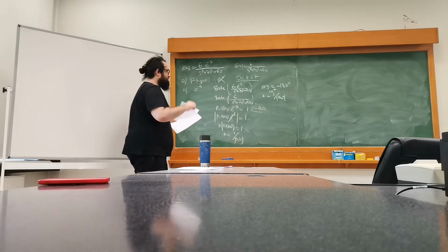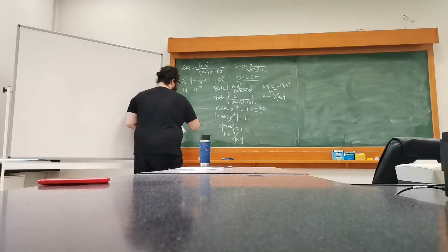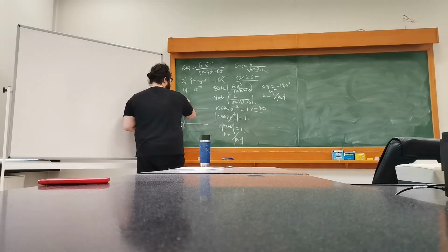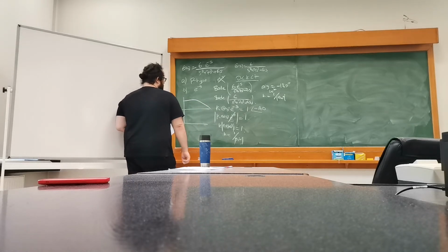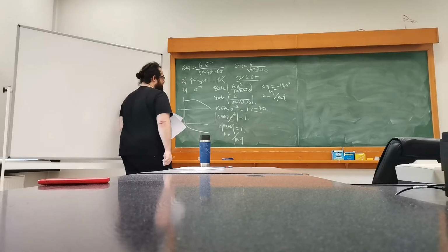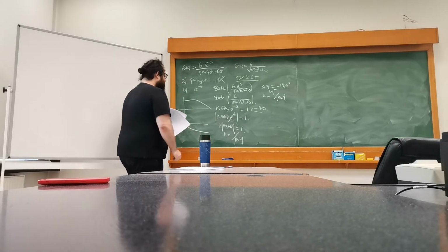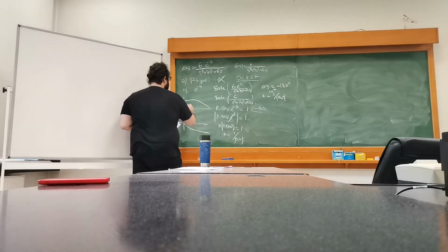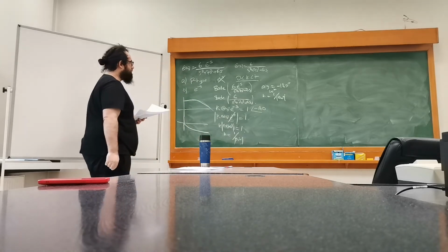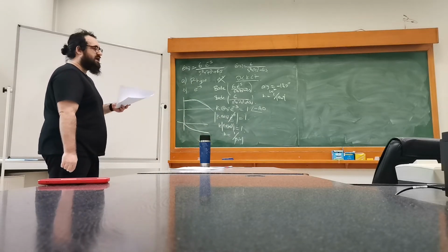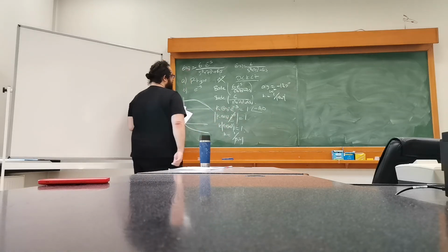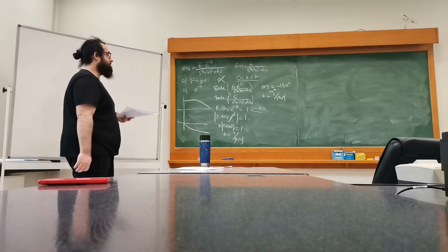So this also means that if we have a certain Bode plot, let's assume that this is the Bode plot. It means that if we add the delay to the system, we will again have the same gain, because it doesn't really affect the gain value here. I didn't sketch it very well, but you will have the same gain.